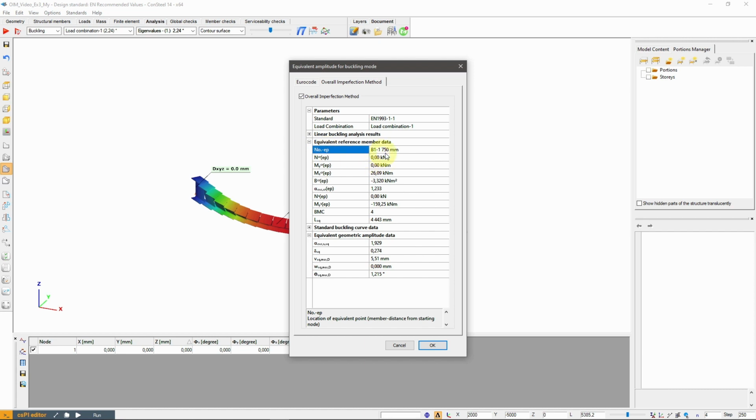As we can see, the equivalent point is not in the middle in this case. This is because the buckling shape is not symmetrical, since the loading is not symmetrical. Also because the moment distribution is not a fully uniform constant distribution, but a triangular one, we have a more favorable setup compared to the fundamental case, which means that the equivalent length will be shorter than the original 5 meters.